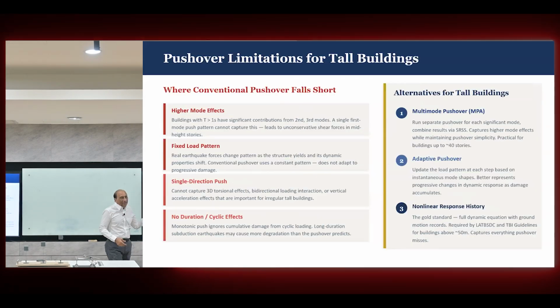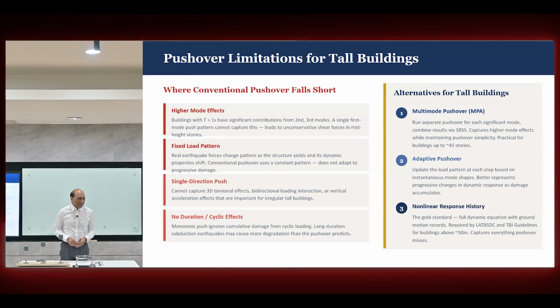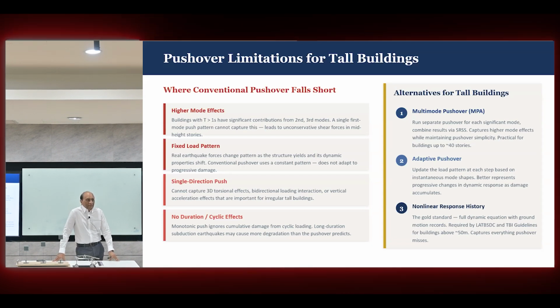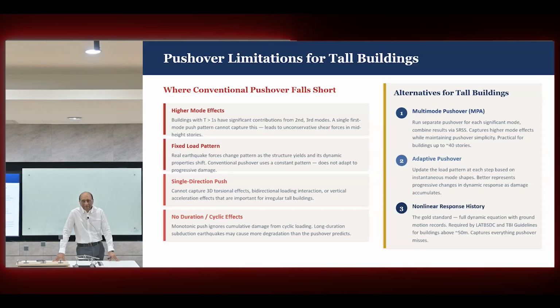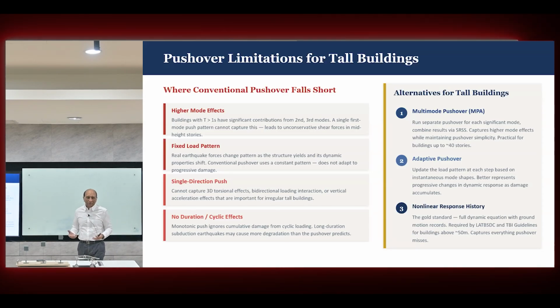So once again, why did people stop using it? Same reason why response spectrum has limitations. It's very similar in that way: it is very good, but it has limitations. Number one, higher mode effects cannot be captured because you do one mode at a time. Modal combination, multi-mode pushover did not solve the problem properly. Same problem as response spectrum, but now with nonlinearity. Number two, the fixed load pattern. We already prefix how the load will be applied. A real structure will not be like that, especially in time history.